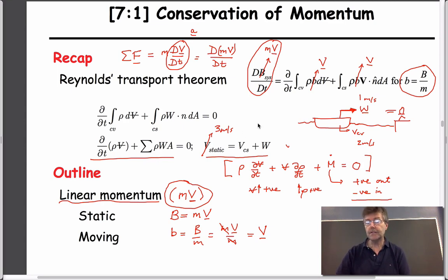We should just realize that with the substitution of this new term, we end up with a new expression which says that the sum of forces applied to a system have to be relative to this, a rate of change of momentum due to our convective accelerations. And this is, if you like, a momentum flux.